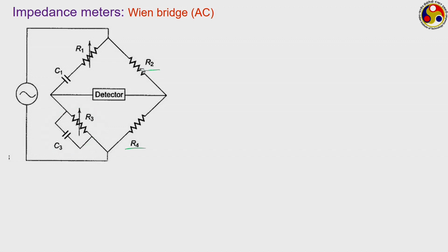Whenever we are going for this kind of circuit, we just alter the Wheatstone bridge relation slightly. Let us say this is our arm 1, this is 2, this is 3, this is 4. Like in case of Wheatstone bridge, we have seen that the product of resistances in the opposite arms are equal to each other. Similarly, here instead of resistance, we write the generalized relation in terms of impedance, which is Z1 Z4 is equal to Z2 Z3, Z refers to the impedance of the corresponding arm.